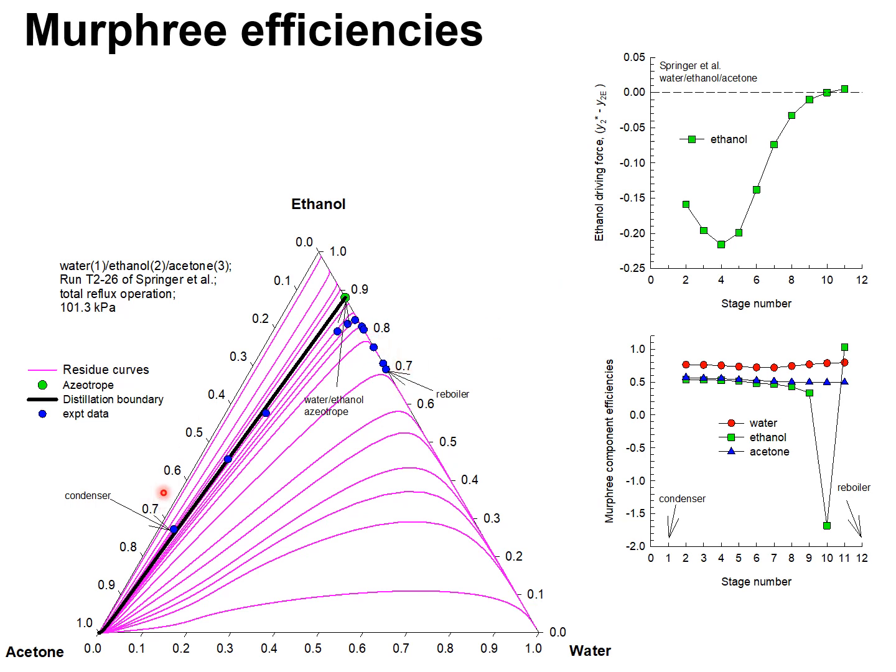From the experimental data for the various trays, the driving forces can be determined, and the Murphree component efficiencies can be calculated using the experimental data on the measured composition entering and leaving the tray, and the vapor liquid equilibrium thermodynamics that were determined using the NRTL model and the DECHEMA database for the experimental data.